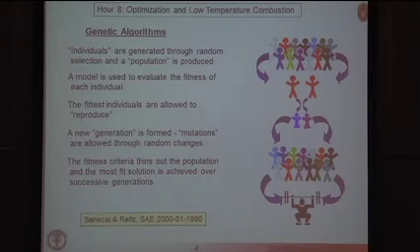Essentially, let's say you're trying to optimize an engine for nitric oxide and particulate. What you'll do is, using your intuition, generate input to a large number of cases that you would then run. So here are all the cases. You then evaluate the results that you get from those cases and pick a couple of them that appear to perform well. You would then create new cases from those parent cases. So you have a new population.